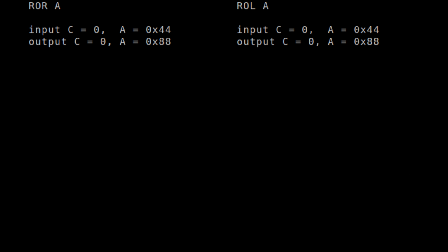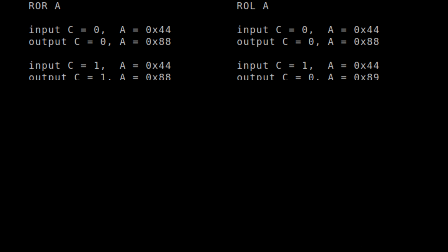So let's summarize. We have seen that the rotation to the right of the accumulator behaves exactly as the arithmetic shift left of the accumulator, since when setting the carry flag it doesn't have any effect on the result but stays unaltered in the flags register.